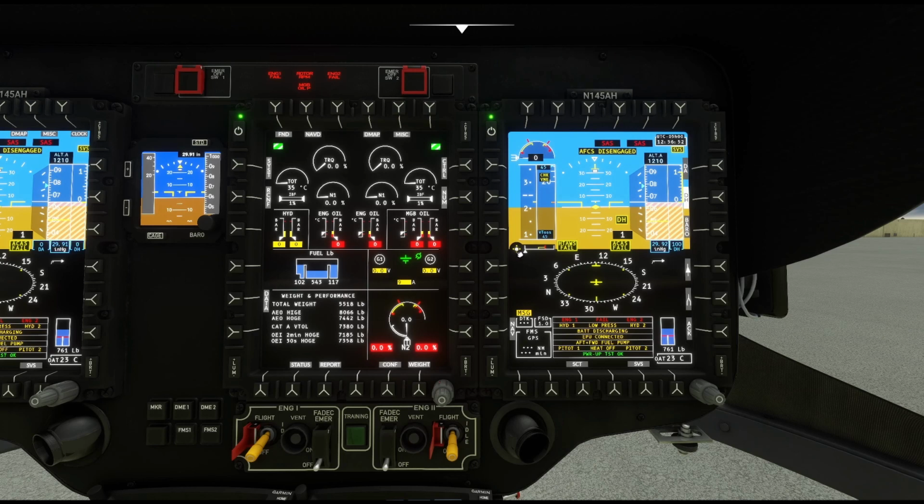So it bends the mast ever so slightly. All right, and actually the main bearing inside of the mast that seats the mast inside the transmission has a spherical type, almost like a ball bearing to it, or like a spherical bearing to it that allows the bending of that mast to be absorbed by that bearing. And this right here lets you know how much you are bending it.